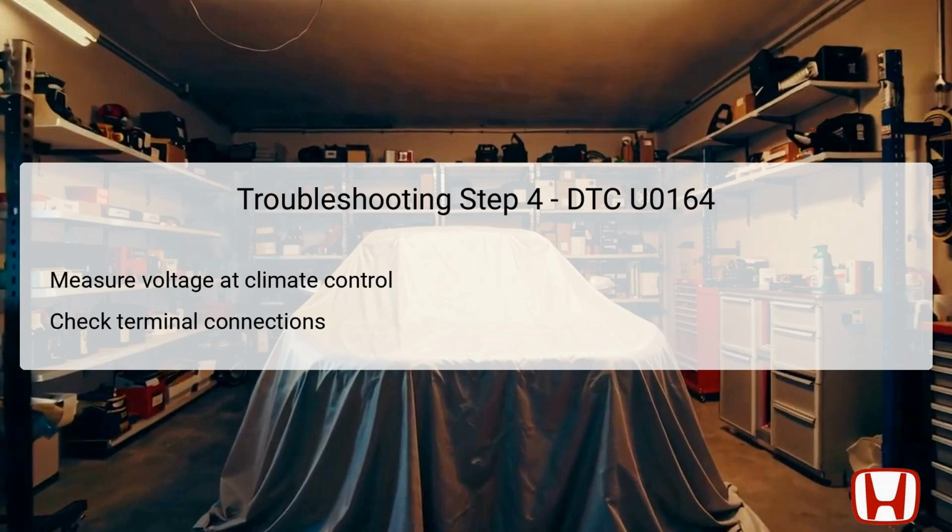If the voltage is confirmed present, it suggests that power is available to the climate control unit, moving the technician to the next step. If battery voltage is absent at this stage, it implies a communication breakdown, likely due to faulty connections or wiring, necessitating further investigation of the circuits leading to the climate control unit.